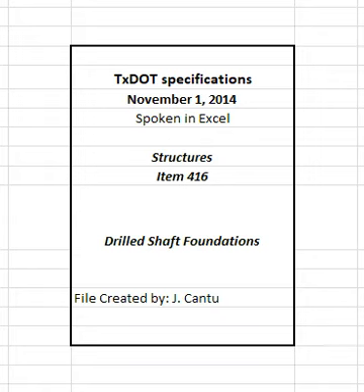Place concrete through a closed tremie or pump it to the bottom of the excavation. The minimum tremie diameter will be at least 6 times the maximum size of aggregate used in the concrete mix but not less than 10 inches. Initially seal the tremie or pump line to positively separate the concrete from the slurry or water. Place concrete continuously from the beginning of placement until the shaft is completed.